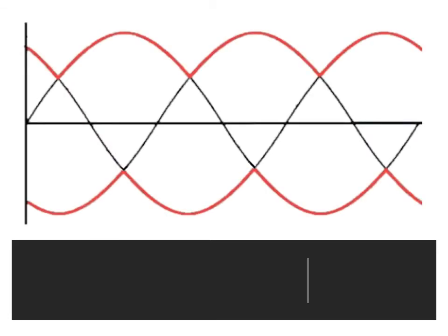If we look at our 3 voltages that are separated by 120 degrees, and then we just look across the top of each, you can see where the voltage never reaches 0 on the positive alternations. Then if you look on the negative alternations, you can see also there the voltage never reaches 0.